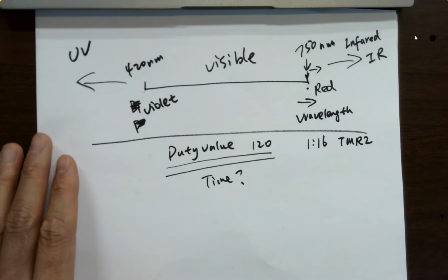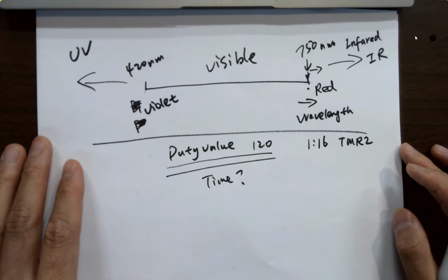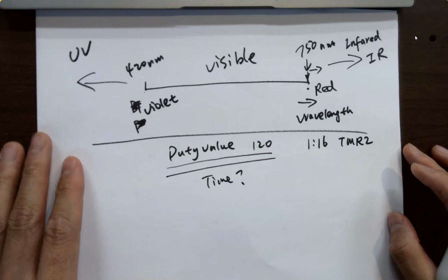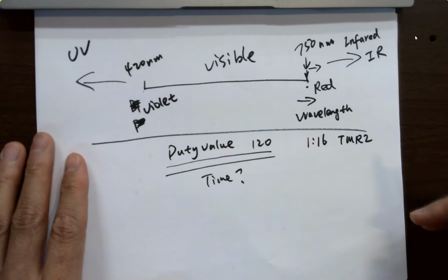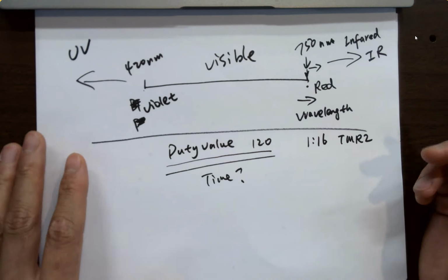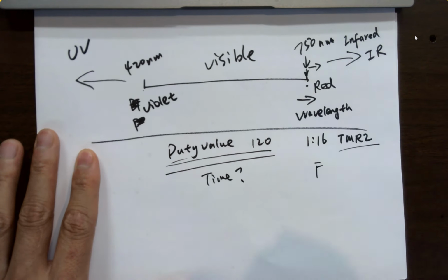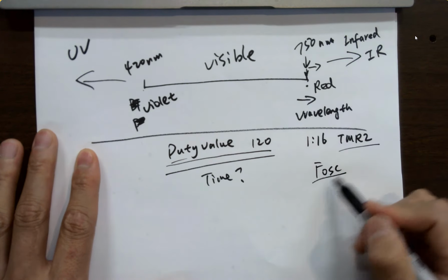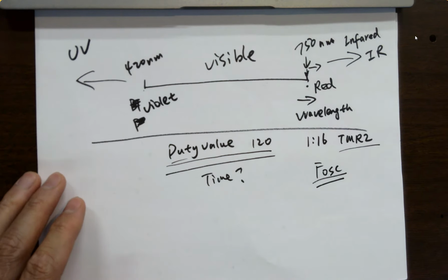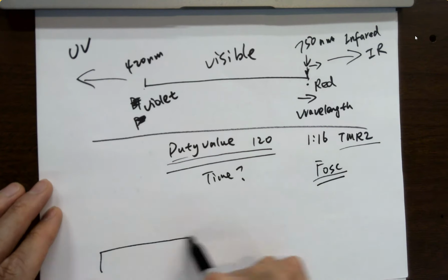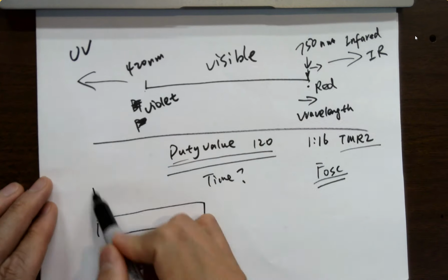For this Timer 2, 8-bit. You ask first, Brandon. For this to be assumed, it's FOSC divided by 4. No, for timer 2, counting for duty value, refer to Monday's lecture. We use FOSC, not FOSC divided by 4. We explained that on Monday. Keep that in mind if you're still not clear on that. So timer 2, I'll address your question after that, okay? So timer 2, you have PR2, and you have another one.